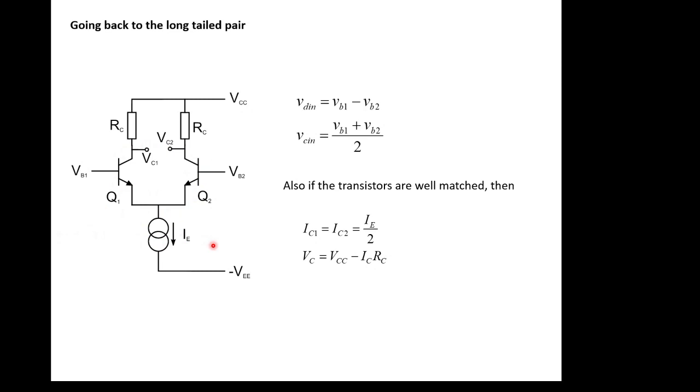And that just makes the common mode gain high, or higher than it needs to be. So well matched, yes, means identical. And the more identical you make these things, the better. It becomes important in things like oscillators as well, because any variation there means the frequency changes, and that's usually not what you want.